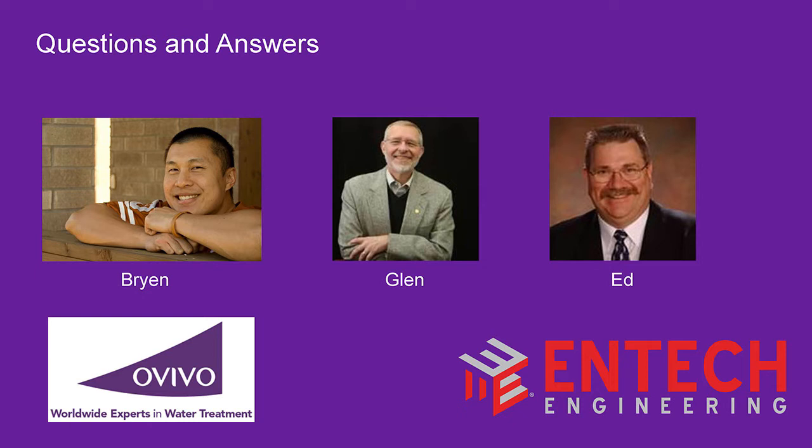The Ovivo, I got to hand it to you guys. You got the design down on a sludge digester diffuser. They just don't clog. And you can clean them out if they do, but I can't tell you I know anybody that's ever had to open up that top and clean it out because they don't clog in the first place. But that's what was there. And I've taken those kind of diffusers out of a couple digesters and been much better off without them.